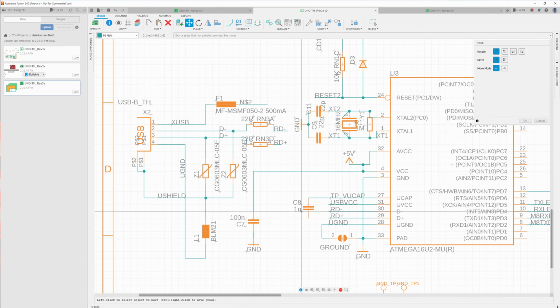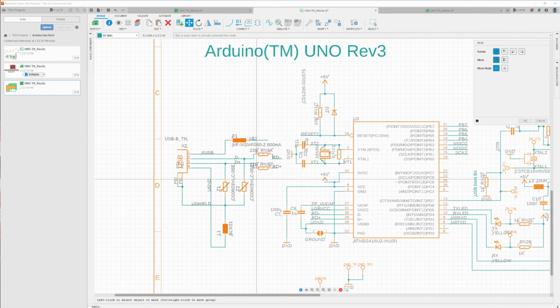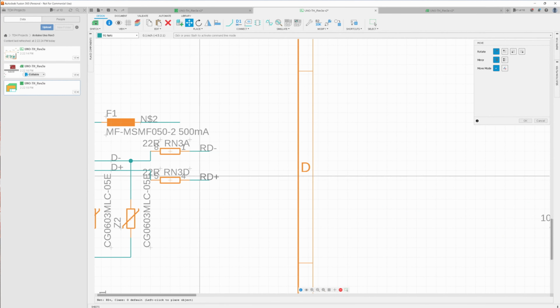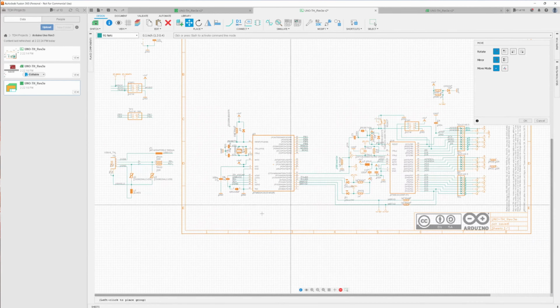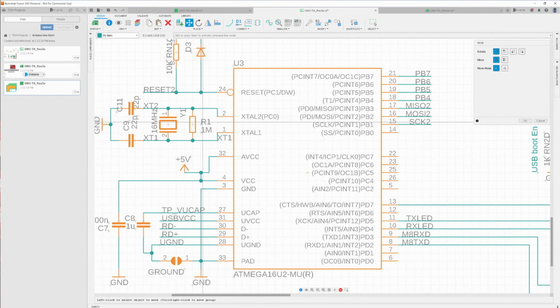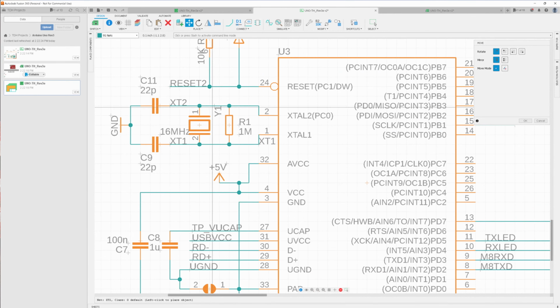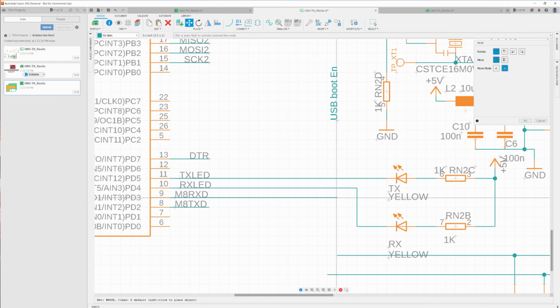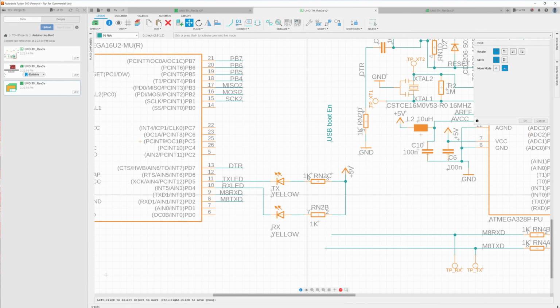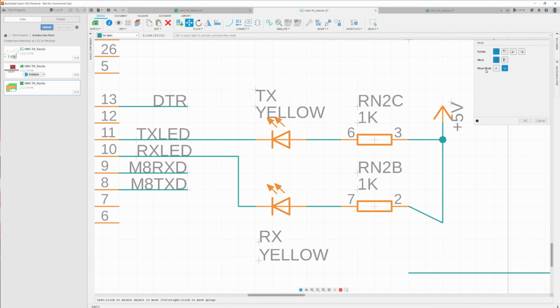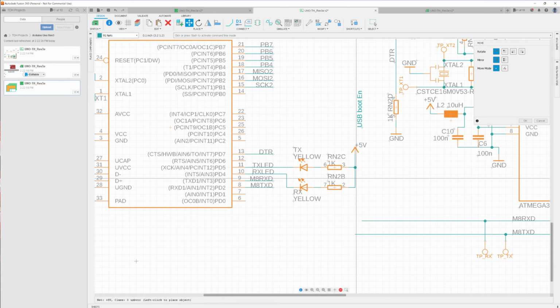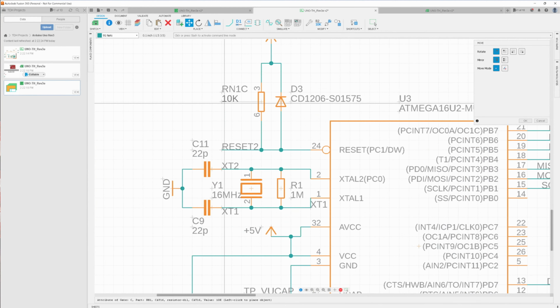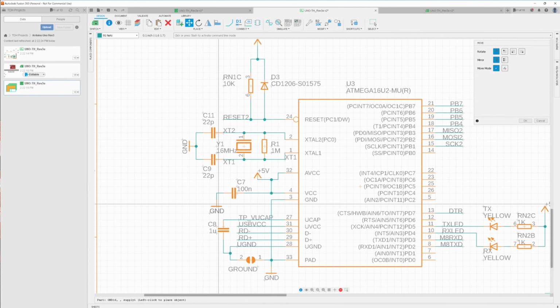The strategy is simple. I like to keep connectors and USB with only the net label and not directly connected. I will keep every part of the schematic that has its own function separate. I will disconnect it by deleting nets and placing labels instead. In this way, when all schematic function blocks are placed out of the frame and nicely edited, I will start to put them back in, but this time organized.